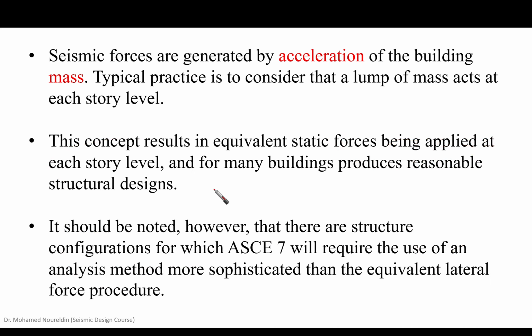Seismic forces are generated by acceleration, as we said, of the building mass. Typical practice is to consider that a lump of mass acts at each story level, and this is right. At each story, we consider that mass is lumped in this story. So we have a multi-degree of freedom system, for example.